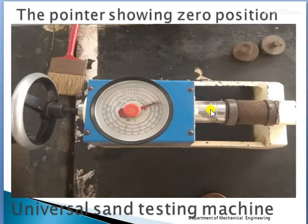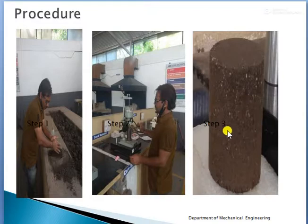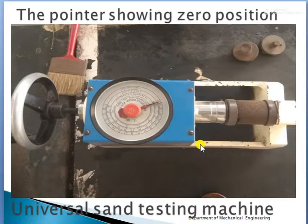This universal sand strength testing machine is used to test the strength of the sand. The compression strength test is done on this machine by replacing the different grippers or pads. The test machine gives a direct reading. Before that, the sand specimen we prepared, 50 by 50 mm, is placed in the compression pads.